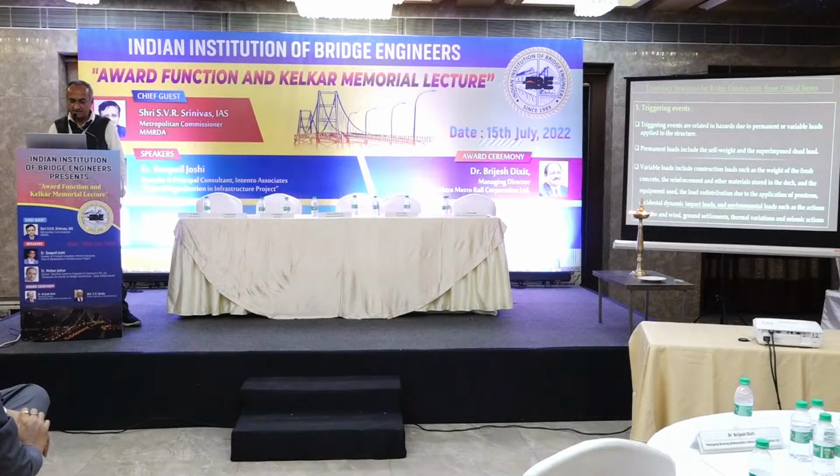So triggering events are related to hazards which are due to permanent or variable loads. Permanent loads are obviously weight of concrete and so on. Variable loads include construction loads like weight of fresh concrete, reinforcement, and other materials stored on the deck, then construction traffic and so on.